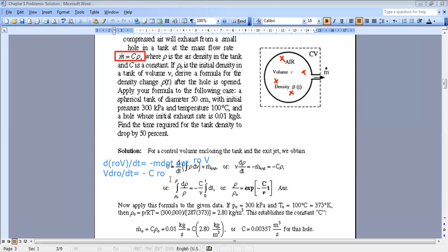It is equal to the derivative of the mass of the control volume with respect to time plus m dot out minus m dot in. So always pay attention: for a system, the mass is constant, but for a control volume, it can be variable. This is why the first term is always 0, because it represents the derivative of the system mass with respect to time. You can understand this more if you go back to the material and replace in the equation of the Reynolds transport theorem.